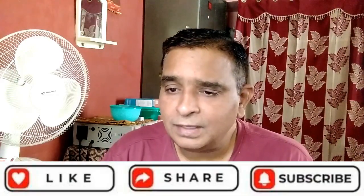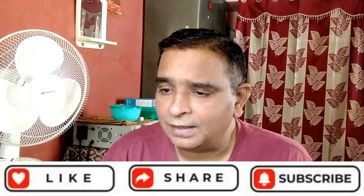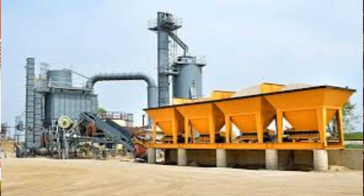And the next point is, what is the full name of cement? The full name of cement is Portland cement. The resulting hard substance called clinker is then ground with a small amount of gypsum, that is CaSO4.2H2O, into a powder to make ordinary Portland cement, the most commonly used type of cement, often referred to as OPC.